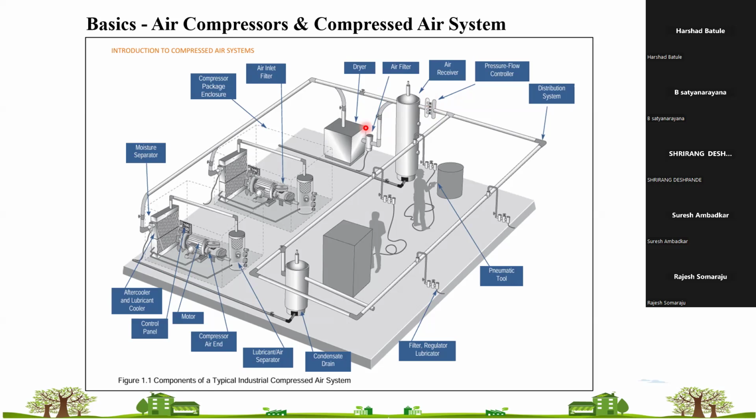If the user has a higher requirement, they will create an additional buffer. Volumetric shocks or surges occur in shot blasting, or in CO2 cleaning where direct purging of air is done. So they need additional receivers in that particular system.